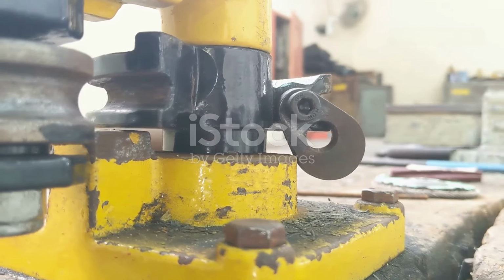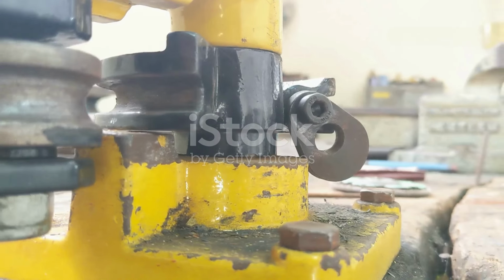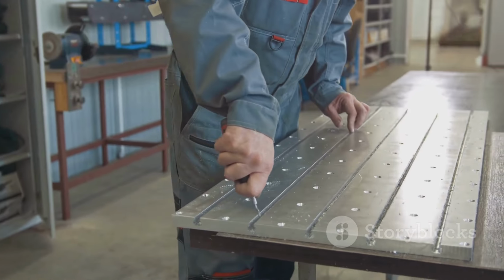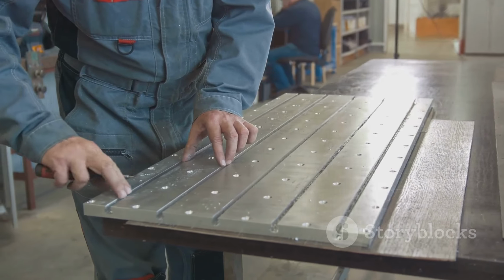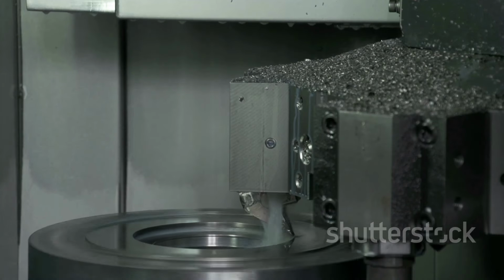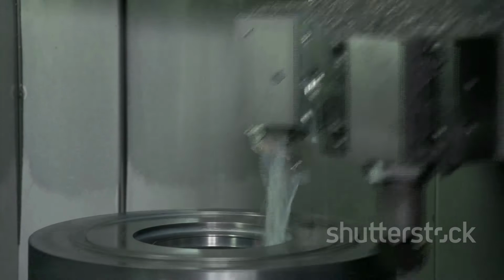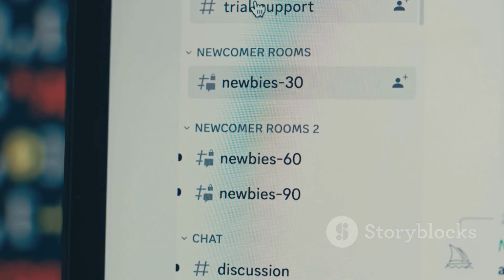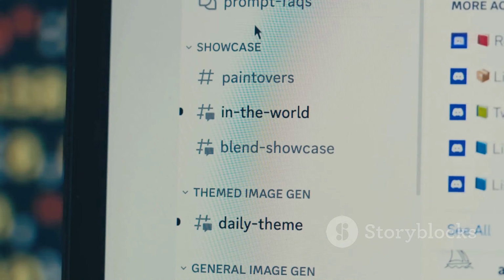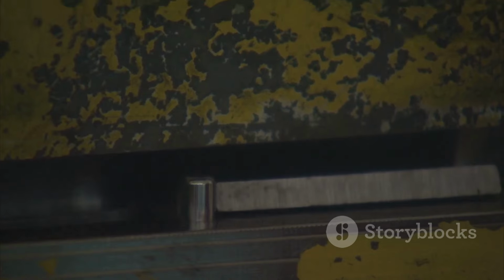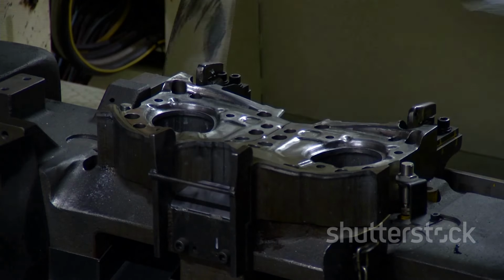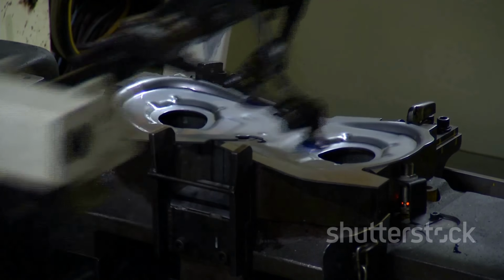The Edge Flange tool is our go-to for creating those classic sheet metal bends. Select the edge we want to bend, specify the angle and direction of the bend, and voila! SolidWorks creates a clean, precise flange along the selected edge. The Edge Flange tool offers several customization options. We can control the flange length, relief cuts at the corners, and even add bends to curved edges. This flexibility allows us to create a wide variety of shapes and forms, from simple boxes to complex enclosures.